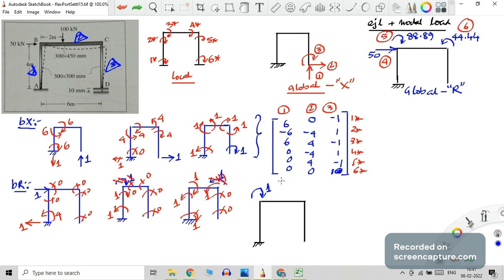I'll explain that. What you have to do is, of course, by drawing this diagram, you cannot decide the quantity divided into 2 star and 3 star. That is not possible. No method available. So you have to start doing the equilibration. When you start doing the equilibration, it is preferable that you follow something like this. See, 1 star is applied clockwise, so the support reaction should be only at A, one support is there. D is supportless, so A has to carry that equilibrating moment. So that is anti-clockwise, isn't it? Anti-clockwise 1, because applied is clockwise, so anti-clockwise 1.